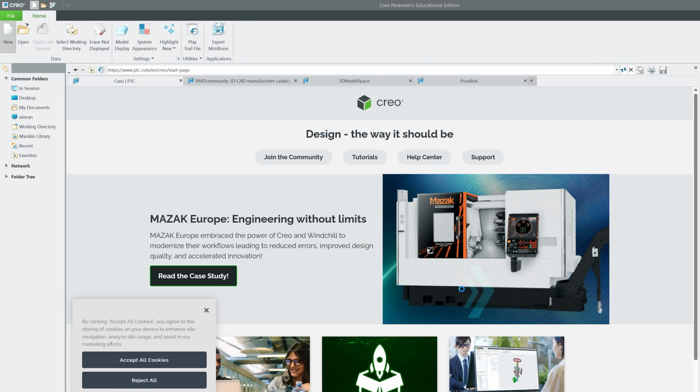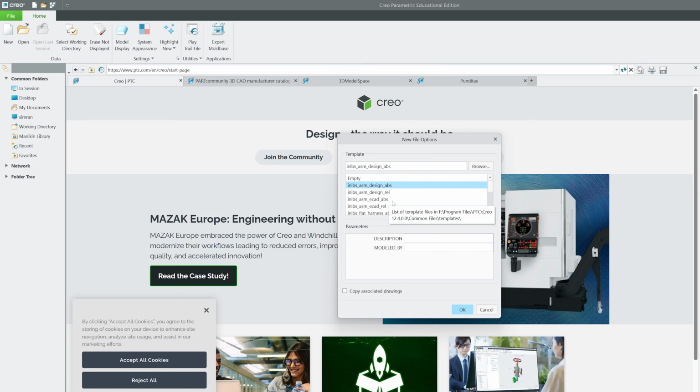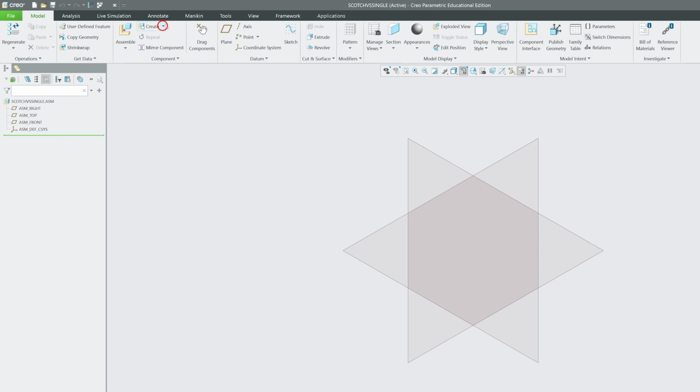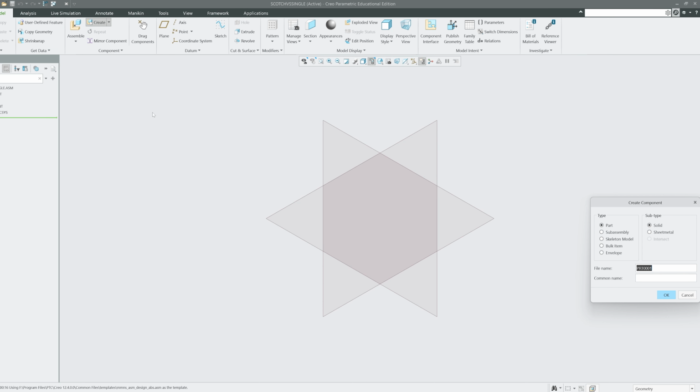And now let's click OK. And probably I need to customize the configuration file, because I am not from a country where the inch pound system is being used. So let me choose millimeter Newton second, assembly design with absolute accuracy. Alright, so now let's create our first component. I prefer to create the assembly first, and then we can add components. So let's add base first.